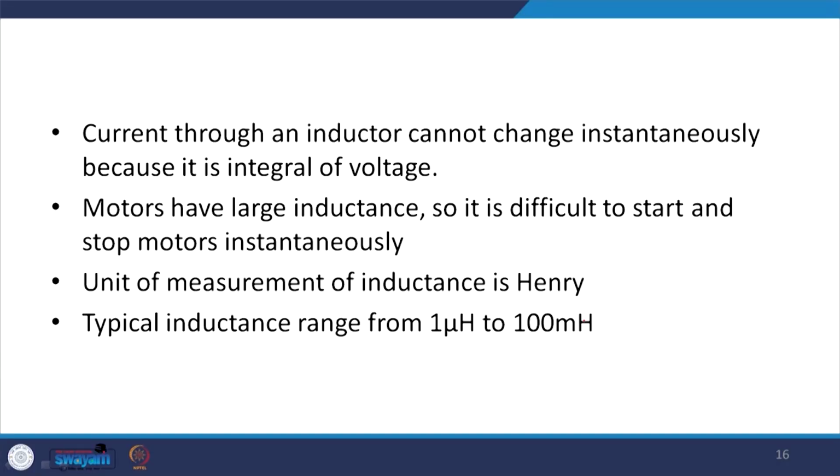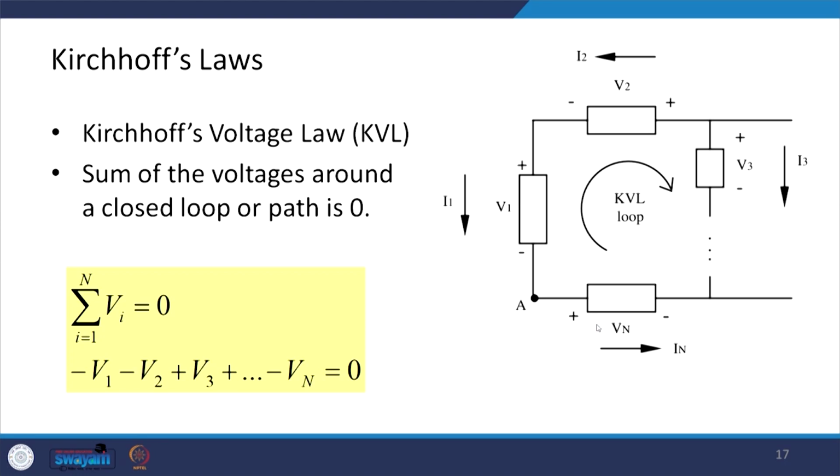So, if your motor has large inductance, it is difficult to start and stop the motor instantaneously. Okay. And the unit for measurement of inductance is Henry, and the typical inductance range is 1 microhenry to 100 millihenry. Okay. So, these are the values.